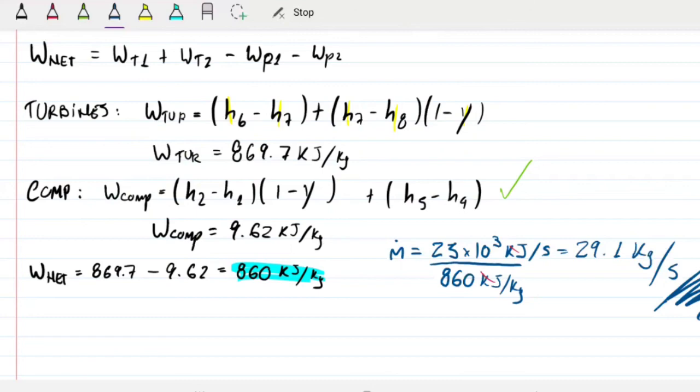But then through the second turbine, the condenser and first pump, we only have about 10 kilograms of water going through, right? So we have, no, I lie, 65%. So it's about 20 kilograms of water going through turbine 2, condenser, and pump 1. Whilst at the same time for the feed water heater and the process heater, we have about 10 kilograms of water going through.